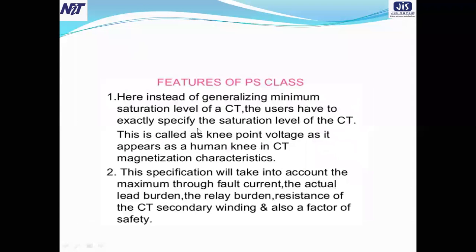So here are the features of PS class. Instead of generalizing the minimum saturation level of the CT, the user has to exactly specify the saturation level of the CT. This is called the knee point voltage, as it appears like a human knee in the CT magnetization characteristic. These specifications will take into account the maximum through fault current, the actual lead burden, the relay burden, the resistance of the CT secondary winding, and also a factor of safety.